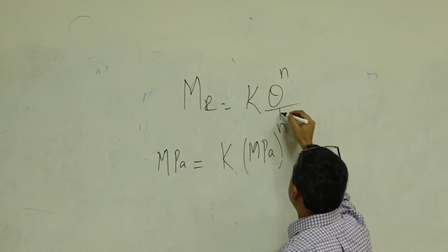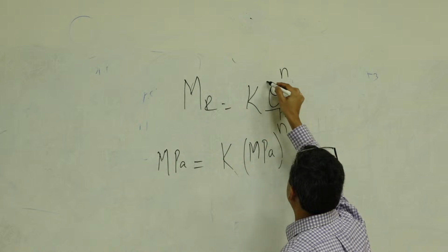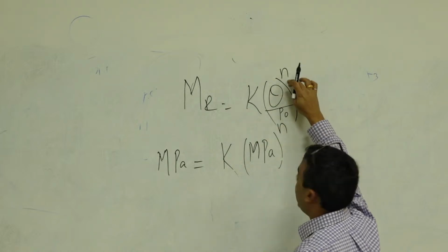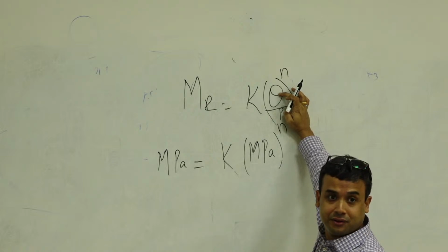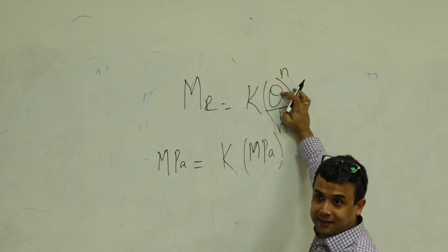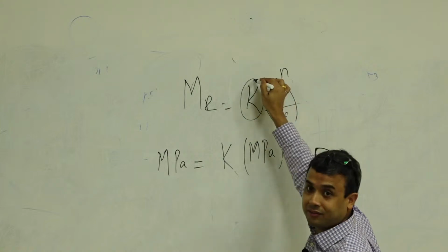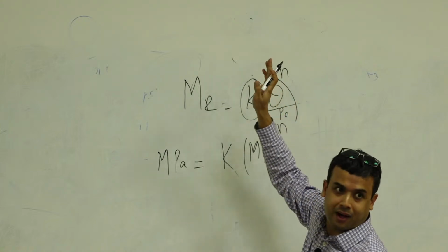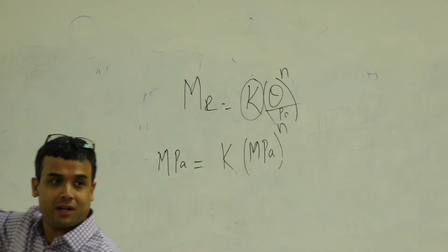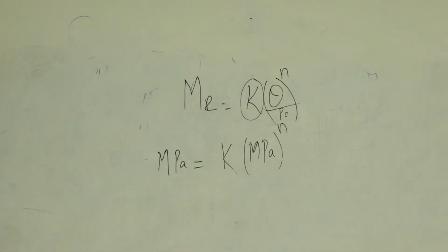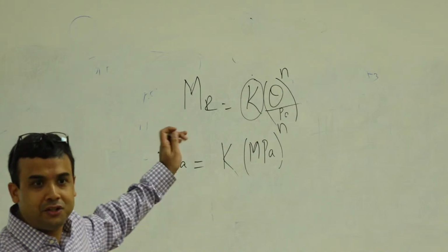Okay, so now he's talking. So either P naught or PA or something. Now you're doing theta over PA. So now what is the unit of this ratio? Unitless. So what now happens to the unit of k? kPa, MPa, or whatever, right? So pay attention to this when reporting your test results. When you're writing papers, when you're writing tables, make sure this is consistent.